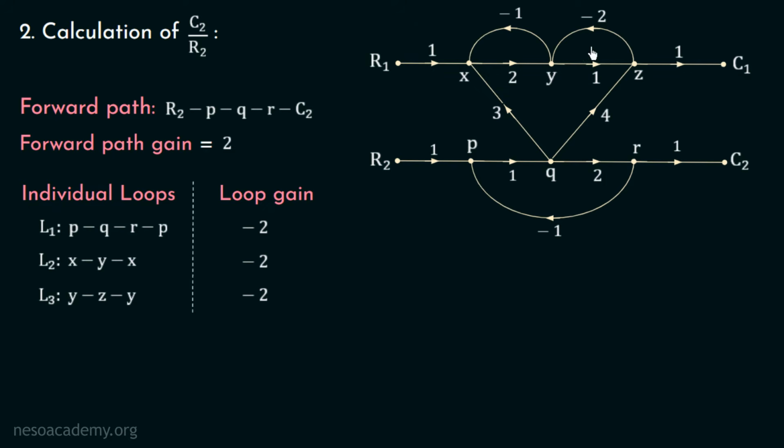Now observe this signal flow graph again and check for three non-touching loops. Yes, the number of three non-touching loops is equal to 0 because we do not have any triplet of non-touching loops. Now we will move on to the calculation of determinant of SFG.